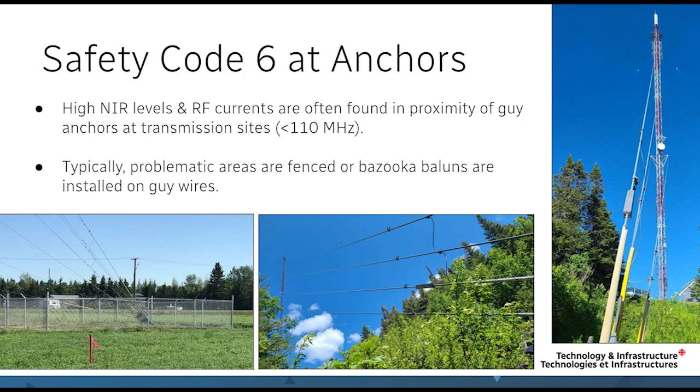We have broadcasting towers hosting our antennas, and then those towers need to be attached to earth or grounded. In situations where the antenna emits radiation near our guys, the guy wires will pick up that energy and transfer it down to the anchors, and we'll have some re-radiation occurring around the anchors. That's a phenomenon that we've been noticing for quite a few years, and we know about it.